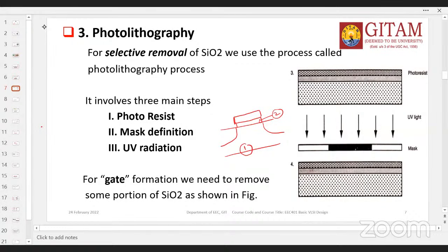Later, with advancements in technology, they maintain very controlled doping concentration. Therefore now they are able to realize the gate oxide perfectly. So for almost 40 to 45 years now, there is no looking back for MOS transistors. They are leading in IC technologies, right? Therefore that is the importance of the gate oxide. Okay, so I should not use the field oxide for gate purposes.